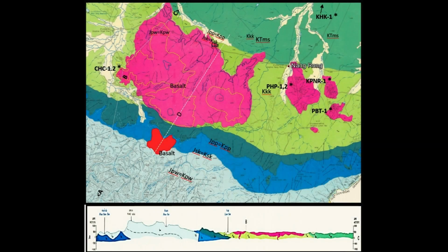Detailed geological map of the Nakhon Ratchasima basalt. The basalt age is 0.92 plus or minus 0.3 million years. The cross-section D is displayed below. Dark blue lines are 200-meter contours, the yellow lines are 250-meter contours and the light blue lines are 300-meter contours. Short dotted lines show fault lines. Note the division between the large flow basalt and a smaller area separated by the Khorat Group, Phu Phan sandstone.